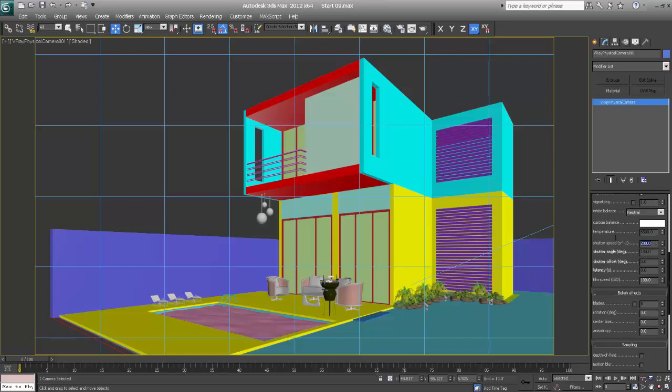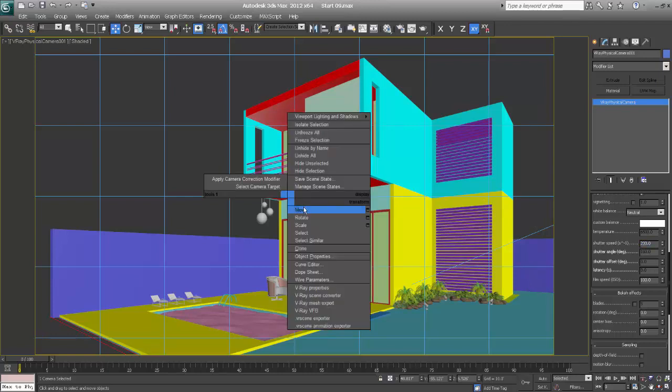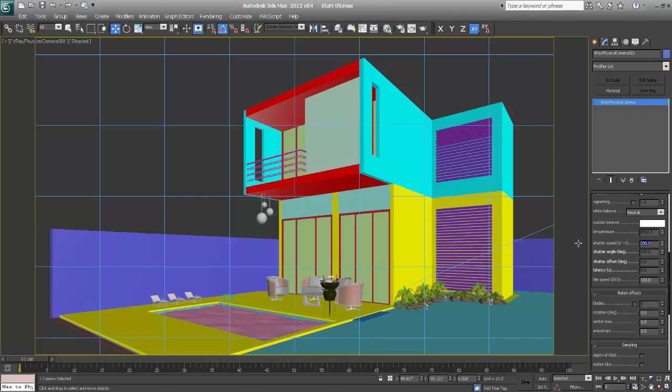And for the shutter speed for day scenes, I usually come down with the shutter speed. If there is a low shutter speed, the maximum light will come in, and if there is a higher shutter speed, less light will come in. So for an evening view, I can always come down, and then we can increase the values gradually. Somehow I'll start with 25, and ISO will be 200. Most of the time you will change these parameters in Vray camera. So we have to take this into consideration. These are not absolute final values. We have to see and check what works well for particular scenes. So I always tell you guys, you just have to be in R&D mode always.